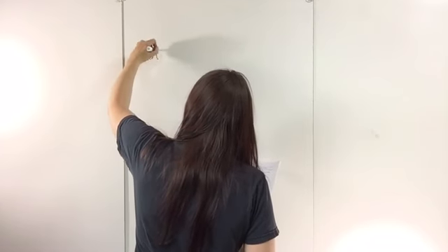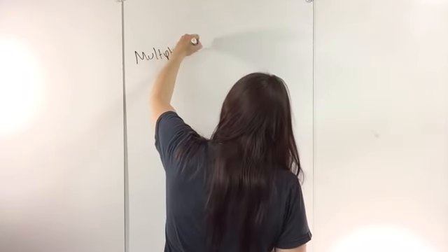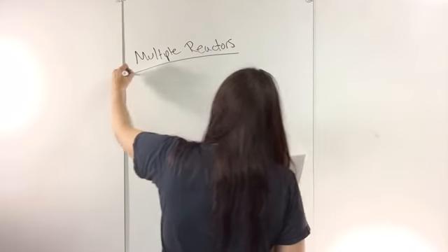So then the next topic was multiple reactors, and that's in chapter 2 and 4. And this is if you have more than one reactor. So it says knowledge about staging reactors, how it affects conversion, performing both graphical, which is the Levenspiel plot, and equation-based calculations. And so I did an example problem with the Levenspiel plots, and I just want to go over that real quick. So this is multiple reactors, and